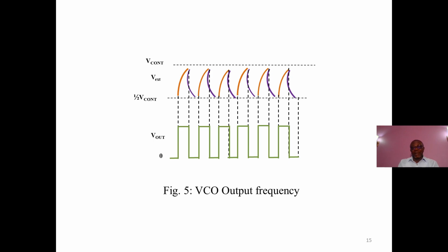But when you are now applying to the control pin 5, you see that instead of acting between 1/3 and 2/3 of the supply voltage VCC, under the VCO, that is as a voltage controlled oscillator, it acts when the value is the value of the control voltage you are applying and when it is 50% value of the control voltage you are applying.